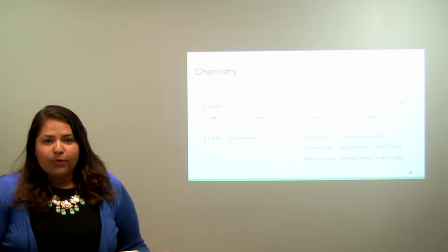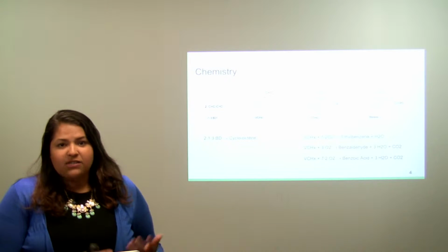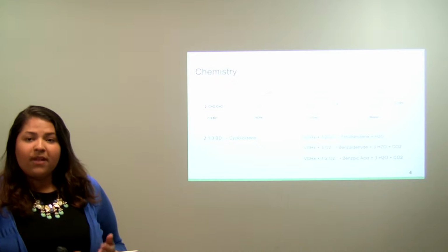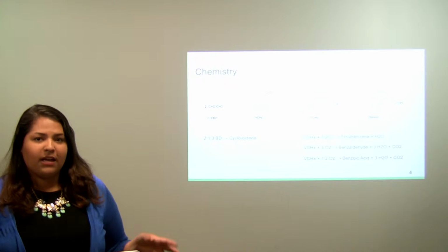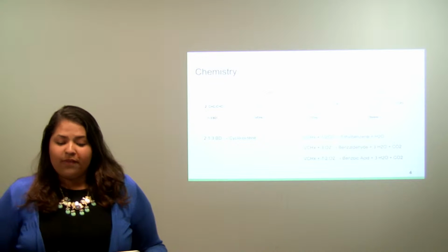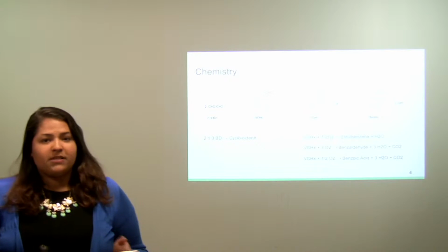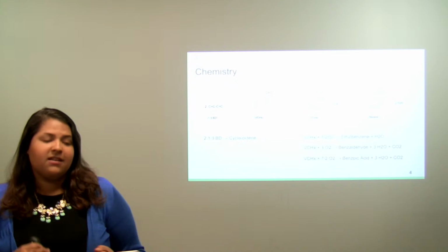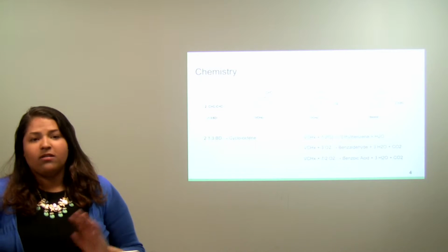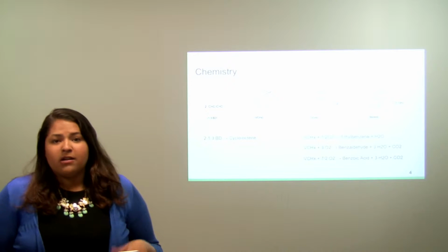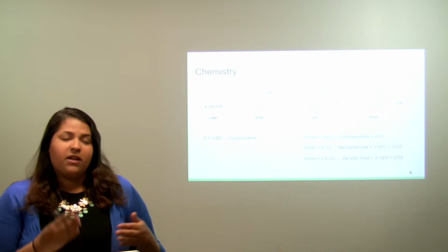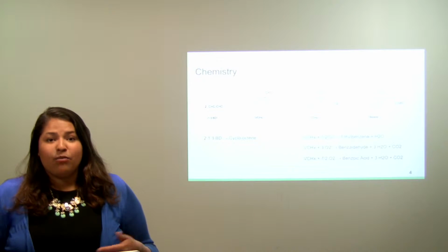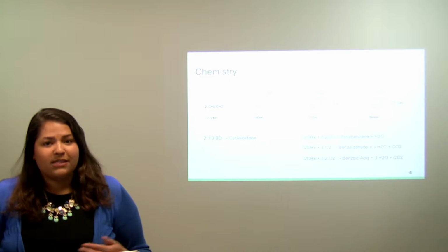Of course, while we're producing the VCHX from the butadiene, cyclooctane is a byproduct that forms, so we're going to go over later how we work to remove that. Another couple of side products that are produced are ethylbenzene, benzoic acid, benzaldehyde, water, and CO2. Those byproducts are produced when the VCHX is being converted to the styrene. We will go over in more detail later how we were able to separate them.